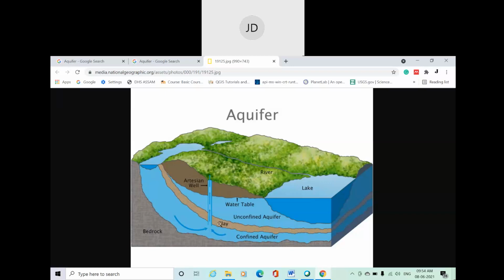So what do we do to get the water from the groundwater? We do boring to the confined layer. You usually go for boring in every domestic area or even industrial area, for collecting water from the ground. Basically it is done on the confined aquifer. From the confined aquifer means what? It is confined from both directions, and we have to create some hole by going for deep boring through that particular area. Below, a rock formation will also be there. From this layer we can collect water. So this is the way we can use groundwater, by using boring or a tube well.